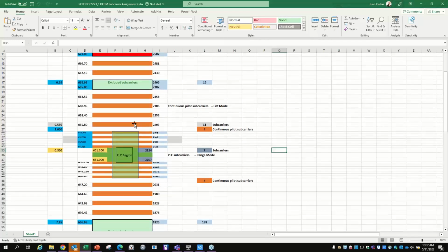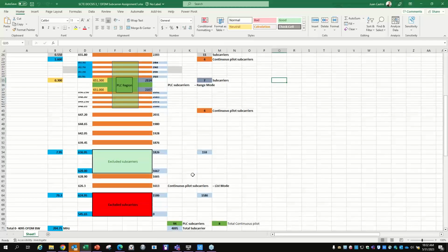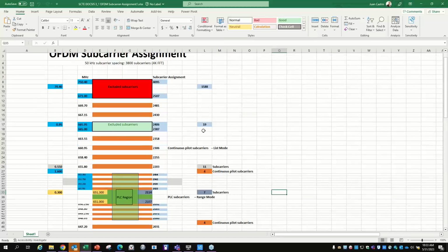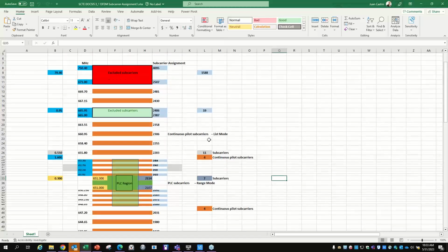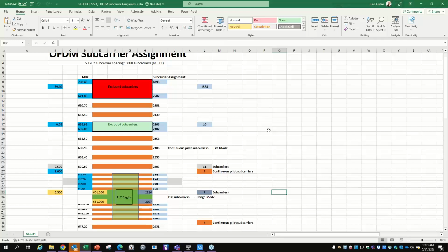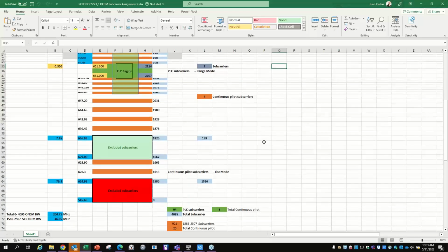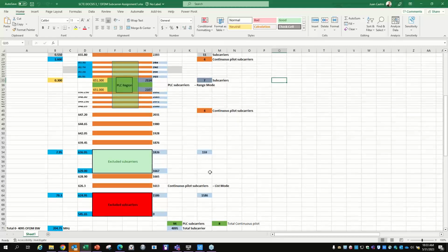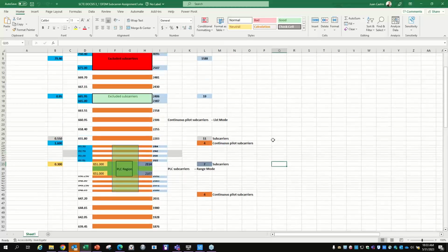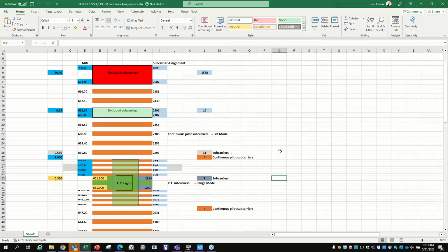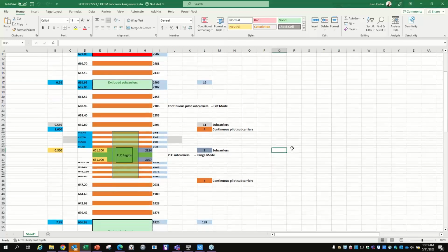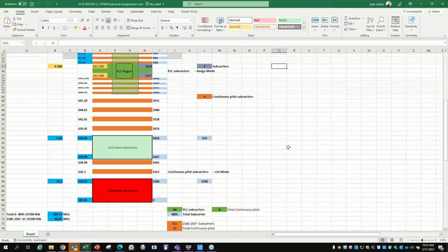So again, the PLC has a region, and it's allocated with pilot carriers on each side to make sure that the modem can scan and detect itself. So again, the OFDM carrier can be broken down in various different ways, and everything is actually allocated. Every subcarrier is assigned a particular modulation, or pilot carrier, et cetera, or exclusion zones. Again, this is just a general example, but in reality, it can be mixed modulations and variations. So this is just an example of breaking down the actual OFDM downstream carrier.